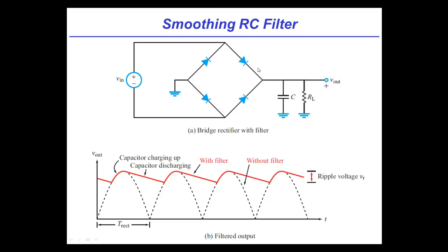Makes sense. And you can think of this as injecting current into this RC. So it charges the cap through those diodes. This current we were talking about goes through, charges the cap. The cap wants to discharge, but it can't because we've picked this RC such that the tau is much longer than this. Okay, so now let me guess.